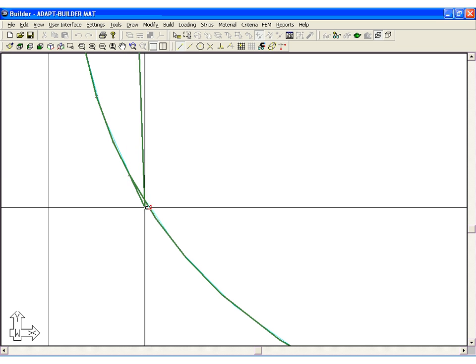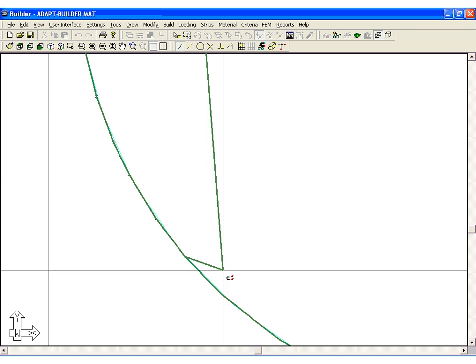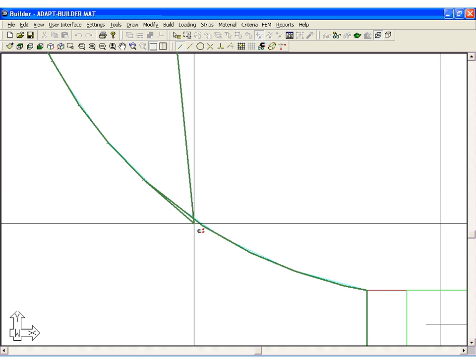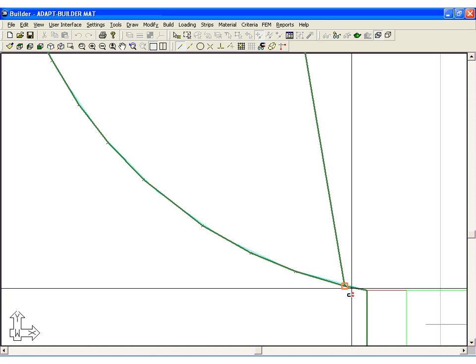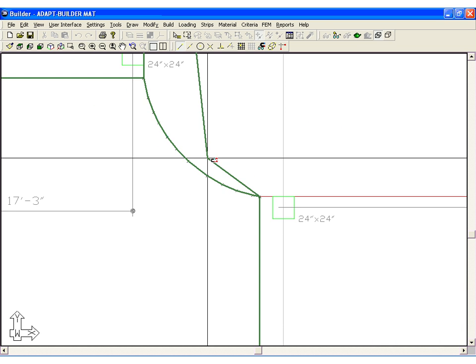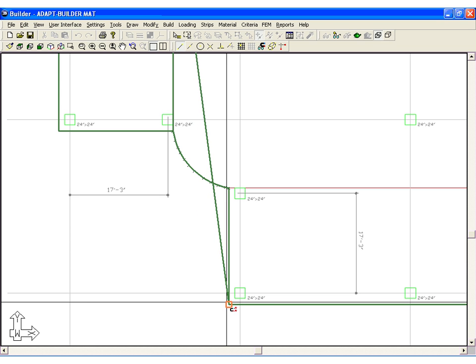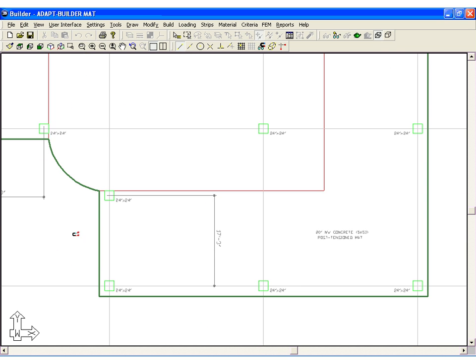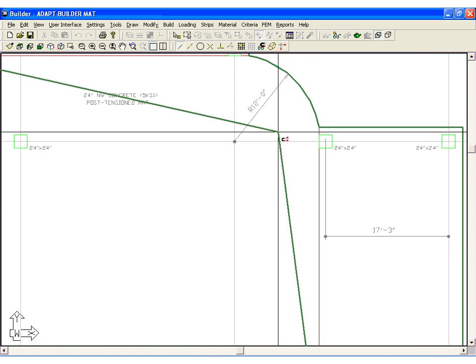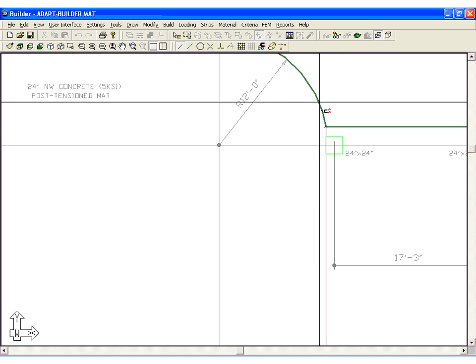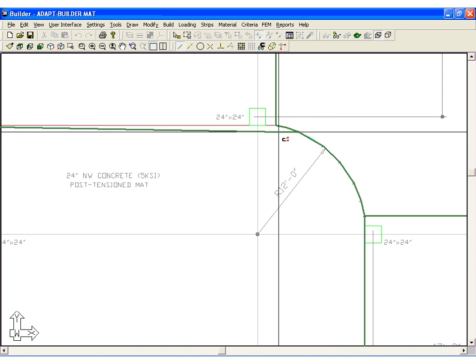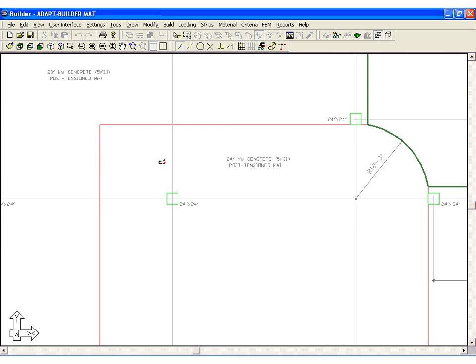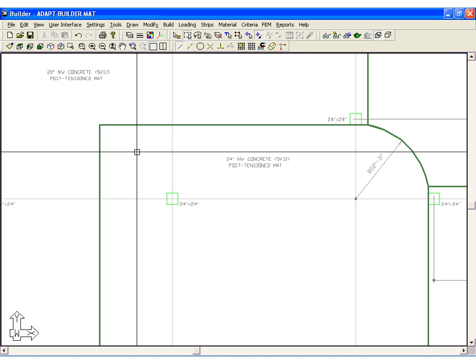And if I click along this slab that's already been defined, you'll notice that the program is finding the different points of those segments that were created, so I can match the slab exactly as it was created the first time around for this arc. And that was a mistake. That's okay. I can just go over to this point, to there, and then back to this point. And again, I'm just creating the edge of the slab by using the endpoints. And then we'll say C to close that slab.